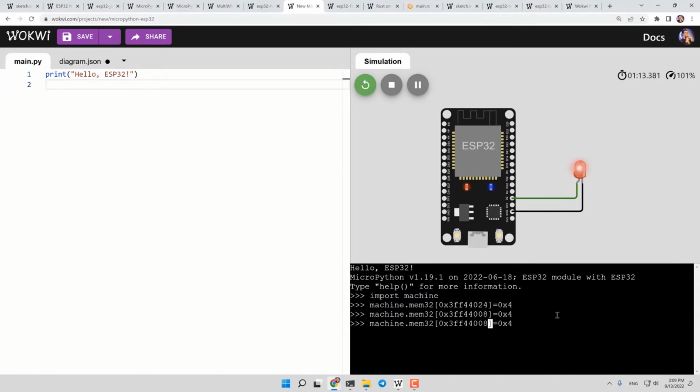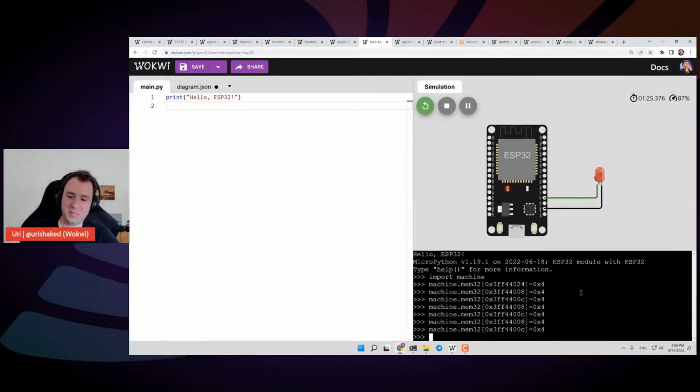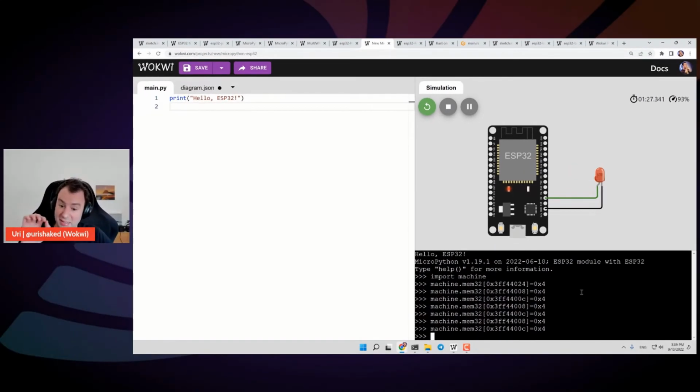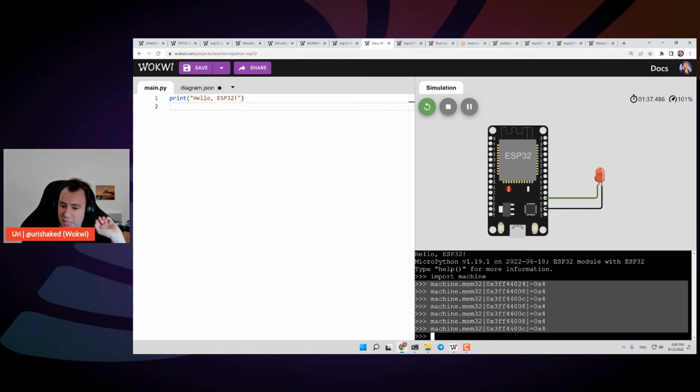And we can also write to another address, this one, to turn the LED off. And you can easily see how we could create a loop that would blink an LED, but I promise no blink program, so it won't be a blink today. That's one of the things I really love about MicroPython. It's simple on one hand, but when you need to get raw access to the hardware, you can do it just like we did today.